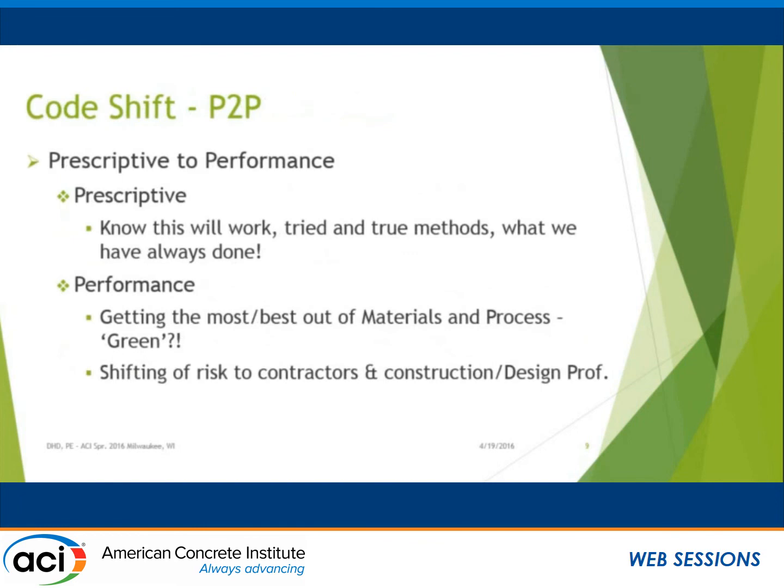There's a code shift, and it's technically termed P2P, prescriptive to performance. Prescriptive is what we know has worked in the past. Essentially, you get a recipe for a mix design, you follow it, and it gives you what you expect. And those are tried and true methods.